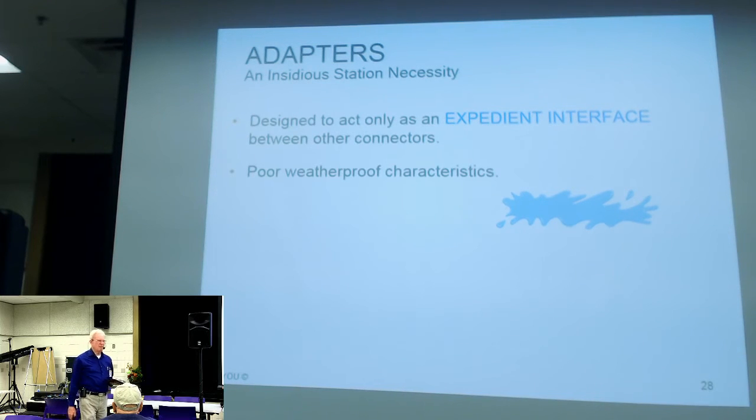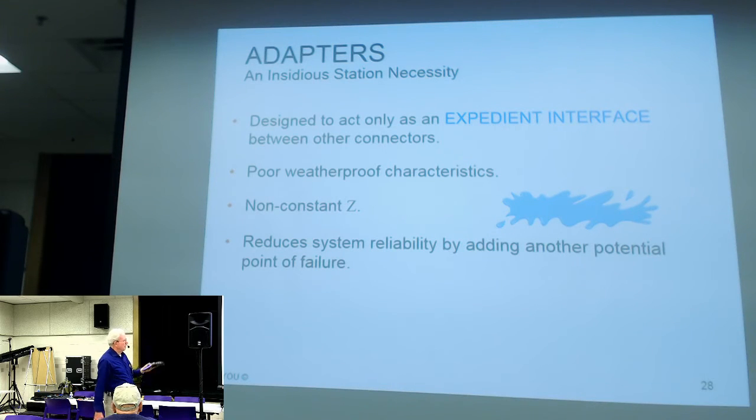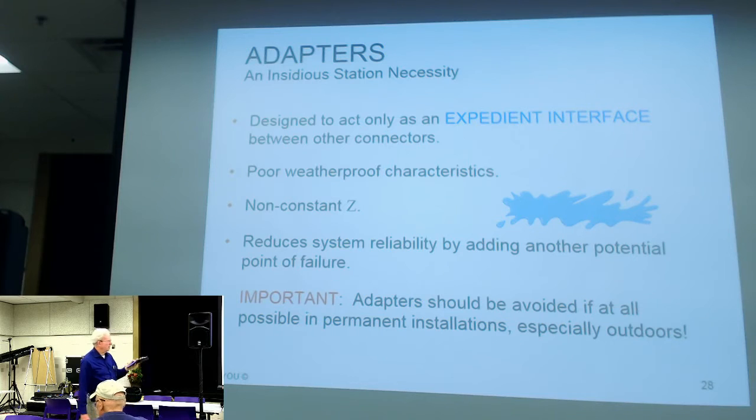Really, you shouldn't leave them in the circuit all the time. And for God's sake, don't put them outside. They have terrible weatherproofing characteristics, non-constant impedance. Just another point of failure. Again, that's just me talking, but I wouldn't think of putting one outside.